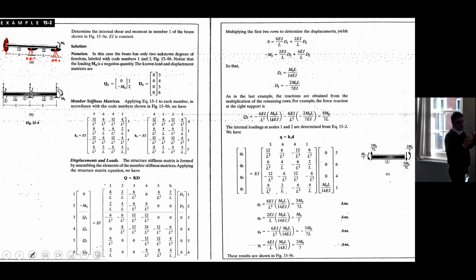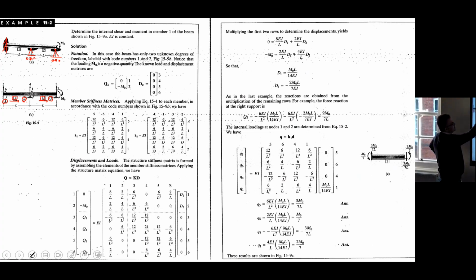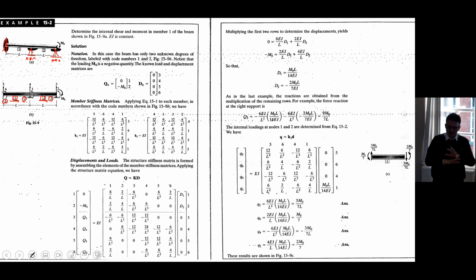For it, let's go through it step by step. We have joint number 1, joint number 2, joint number 3. Okay? These are nodes. We have element number 1, element number 2. This arrow means from near end to far. Right? We have degrees of freedom. I don't write it because it gets messy. Degrees of freedom are 2, 3, 1, 4, 6, 5. Up to you what sequence you're following. It doesn't matter.